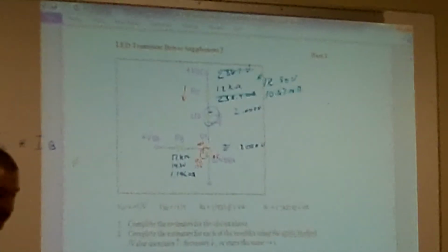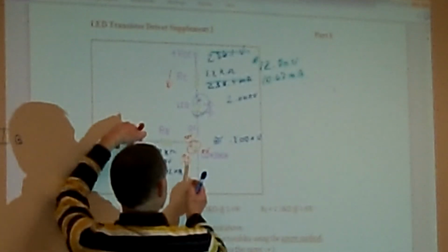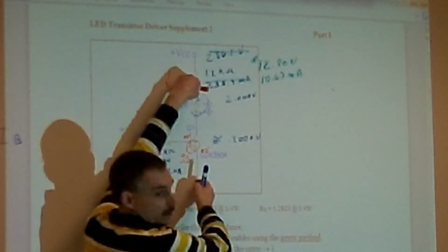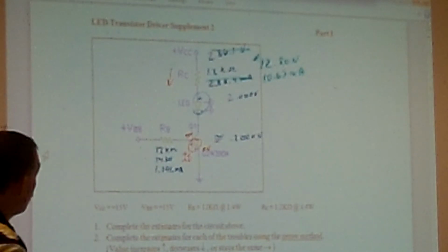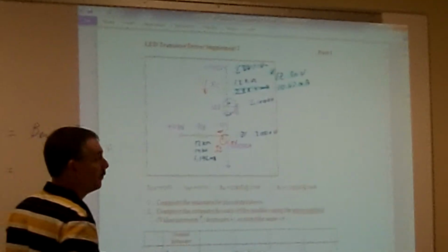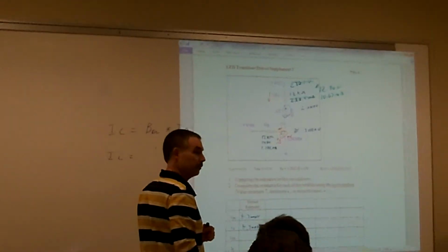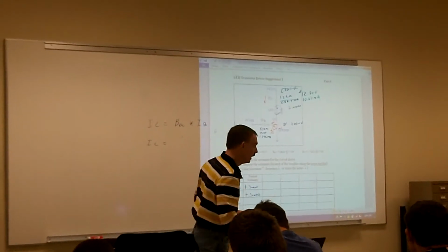Not really, actually we're just treating it as two different circuits. Our base to emitter, that's one circuit. Then our IC to IE. So the Q1 in saturation would be closed then? Yep, Q1 would be closed. It would be just like a switch, on or off.